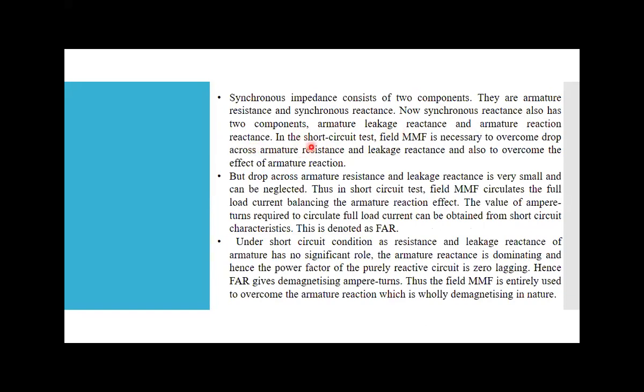So in the short circuit test, the field MMF is required. In the open circuit test, field MMF is required to generate FO or the open circuit voltage. Again, in the short circuit test, we require the field MMF. Why? To overcome the drop across the armature resistance RA and the leakage reactance, and also to overcome the effect of armature reaction.